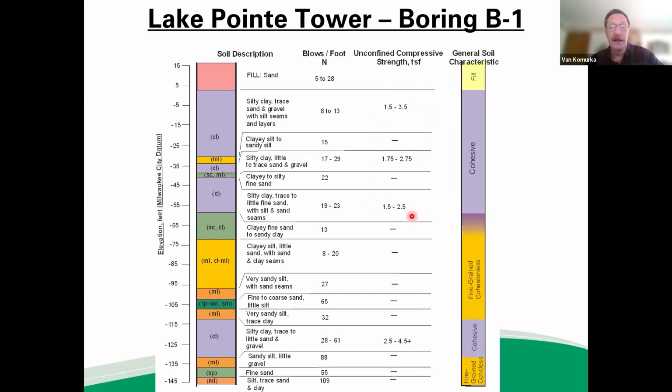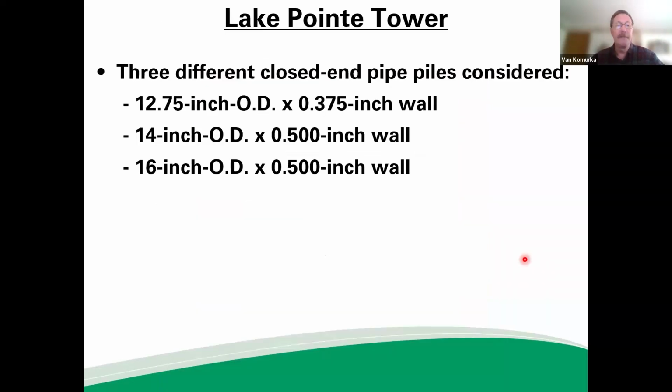All right, nothing out of the ordinary until, again, we get down near the till layer, and then we get some higher unconfined compressive strengths. But nothing that you look at and say, wow, this is an unusual site. Keep in mind these fine-grained cohesionless soils. We're going to see how the setup is affected in those soils, which aren't often given credit for setting up.